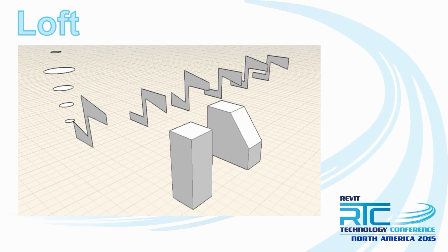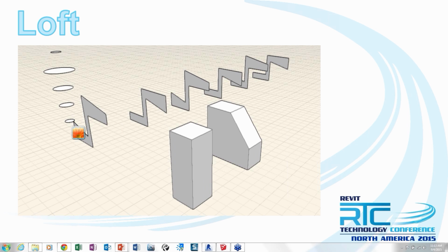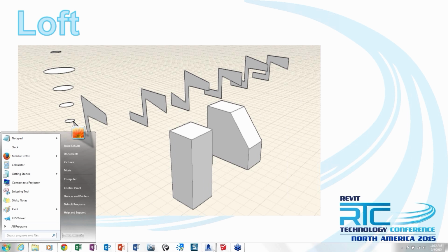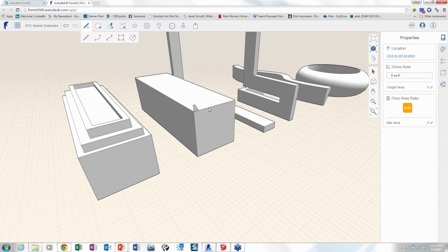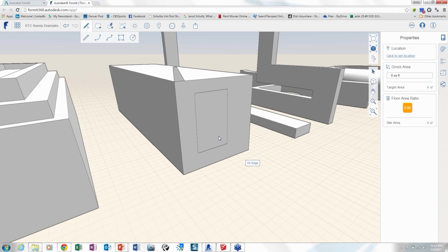Mike has commented that the offset tool is especially useful for windows, making a quick window frame and then pushing it in and applying material onto that face on the inside. You can make that a transparent face. And that reminded me of something else, talking about windows or curtain systems. If you just lay out an area and don't physically do anything with it, this will come across into Revit, and you can actually assign a curtain wall system to that.